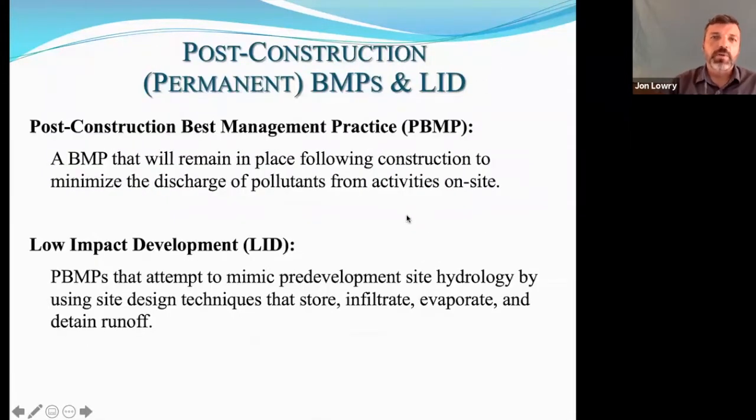Okay, so first of all, what is a post-construction BMP? Often you'll hear the term post-construction, sometimes you'll hear the term permanent. The terms are used interchangeably a lot of the time, but the most proper term is post-construction BMP. As opposed to a construction BMP that's installed for the purpose of controlling sediment and stormwater runoff during the construction process, a permanent BMP is left in place to control and minimize discharge of pollutants from activities long after the project is constructed.